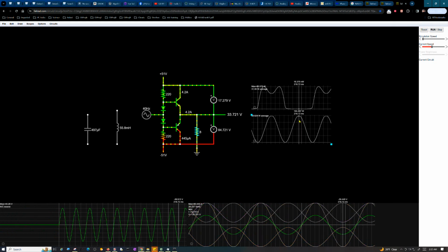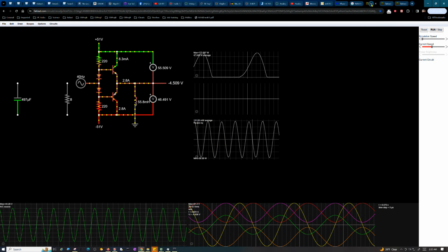But the point is that this is what a resistive load would look like. All the power is above the zero line, like it should be in a resistive load, because on balance it's actually consuming power. If it was below that line, like this, inductance, it would be equally above and equally below. That's a sign it's not actually dissipating any power. Of course, in reality, an inductor would have some resistance in there, and would dissipate some power depending upon what its winding resistance is.